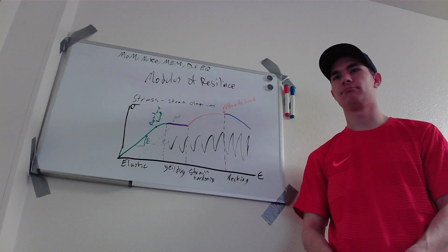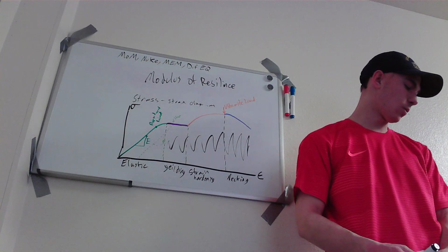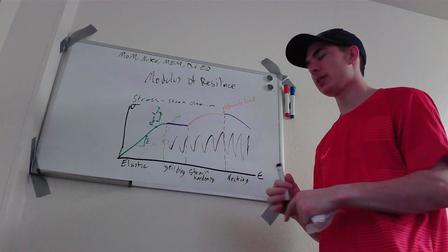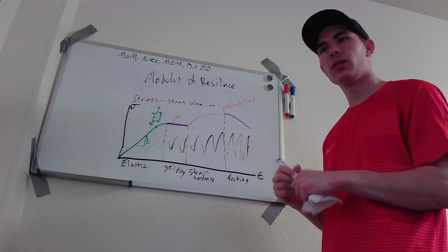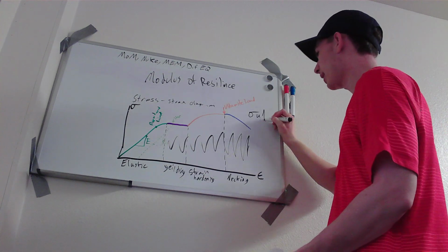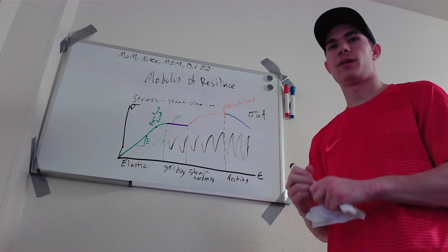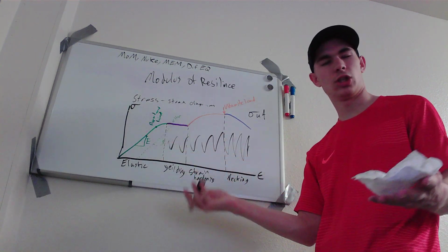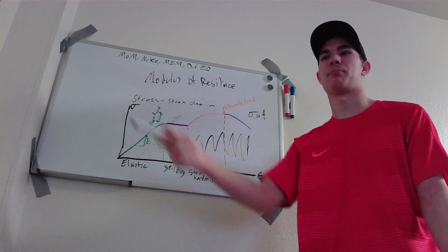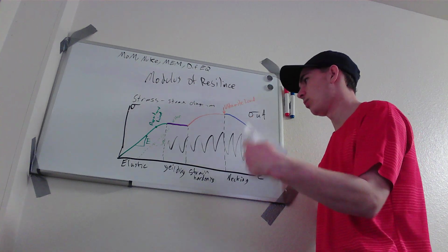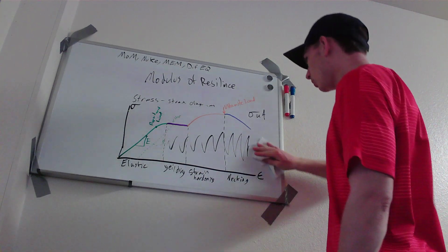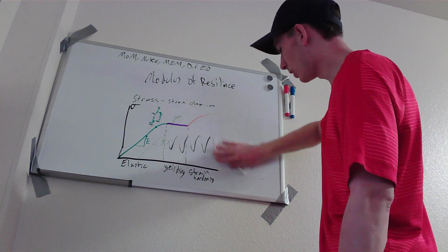That's about it. If you're looking for the actual load, so if this had actual measurements, the actual ultimate load would be found by finding your sigma u, your sigma ultimate, and then multiplying it by that cross-sectional area. That's how you would find your ultimate load or your proportional limit. It's just the cross-sectional area times the stress at that point. And that's how you would go about it. That's what we've been doing in mechanics of materials. Simple, straightforward, kind of cool, kind of interesting.